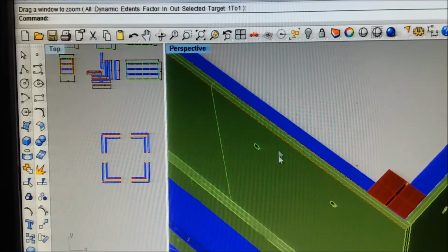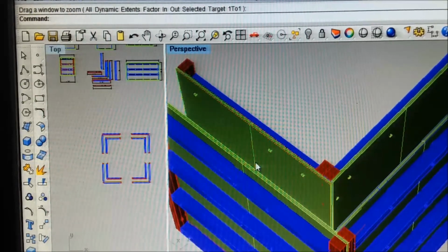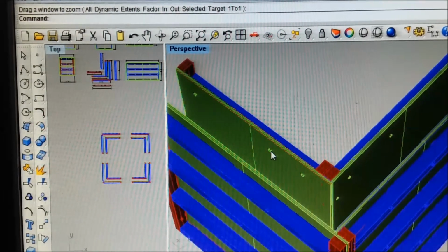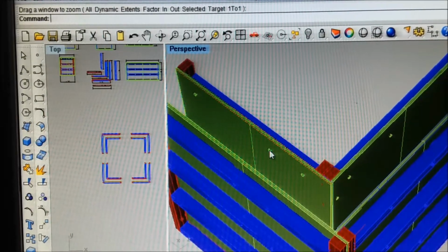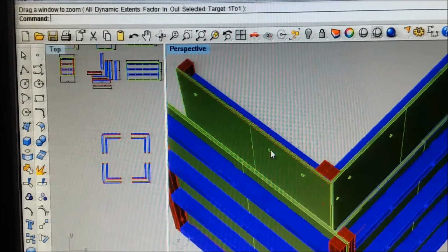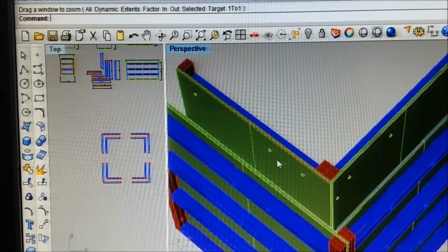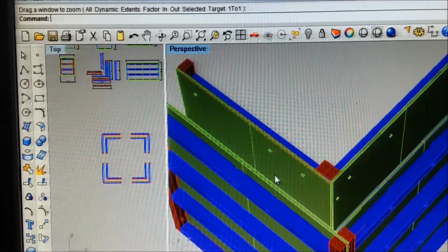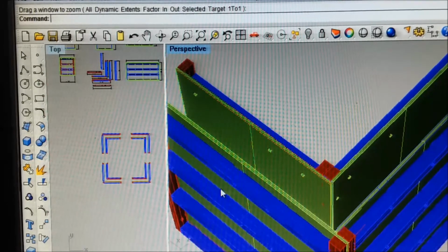To make the thickness of the wall in poured concrete, no matter whether you're using our tall forms or these kinds of forms, you take PVC pipe and cut it. We use a miter saw, but you can cut it with a hacksaw blade with no frame. We've done that too. You cut it to the length for a 7-inch wall. Every place you see one of these holes through the phenolic board, you have a 7-inch piece of pipe, and then you run a piece of threaded rod through it.